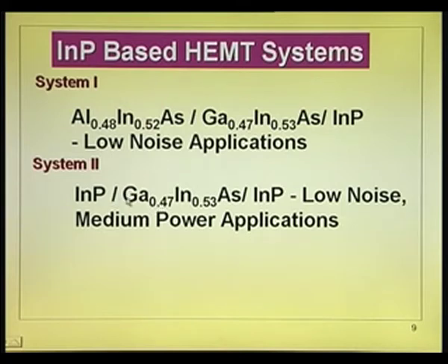The delta EC will not be as high as that. I think you should work it out and see. The neutral level in indium phosphide is not at 2/3 below the conduction band, it is about 1/3 below the conduction band.